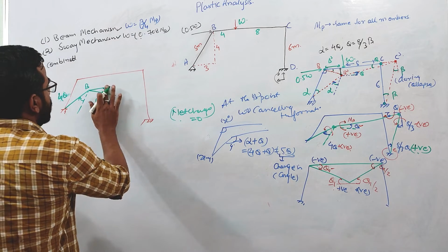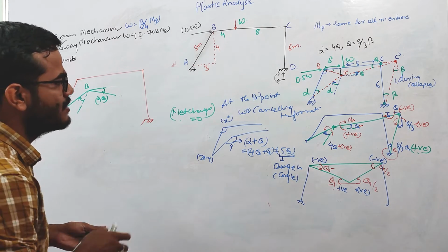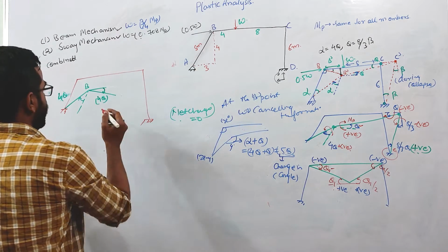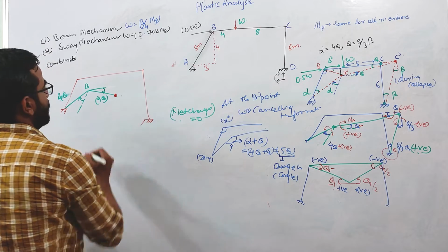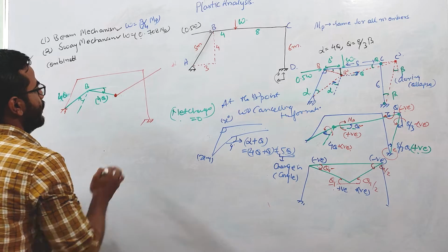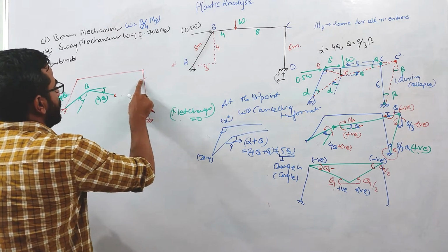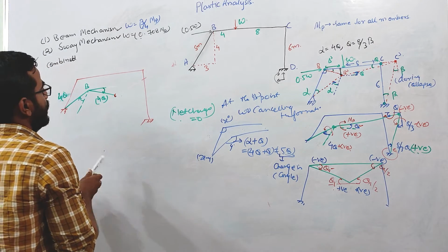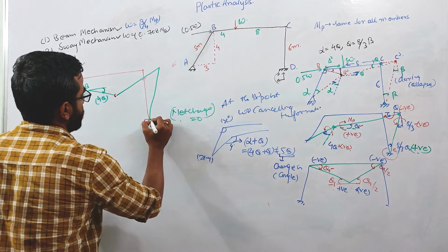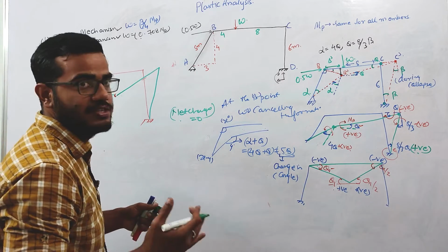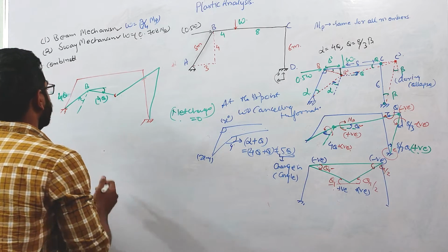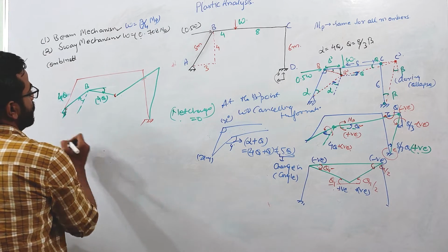Okay, understood? Now, one plastic hinge will form under this point load. I'm showing that plastic hinge. And again, during collapse, it will deform like this. We cannot cancel all the hinges because some mechanism should be there, right? This is a natural hinge.